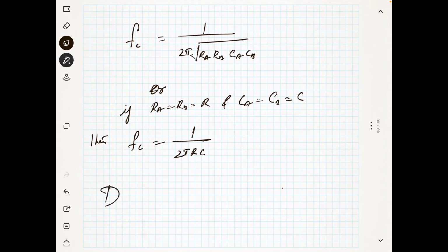And also we have to talk about this damping factor. The damping factor will give you its response. So damping factor is given as 2 minus R1 by R2. So according to the damping factor, you can design this filter, and this will be given from the table.